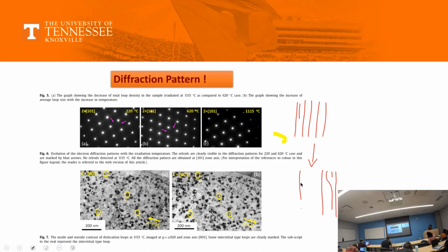With the people I'm discussing the project with here, those who are doing dislocation loops will tell us, first of all, what is the Burgers vector. They will tell us what is g, that would be the planes that you can take out. Then they would talk about something called g dot b analysis, which everyone has to do if you want to be a materials scientist.